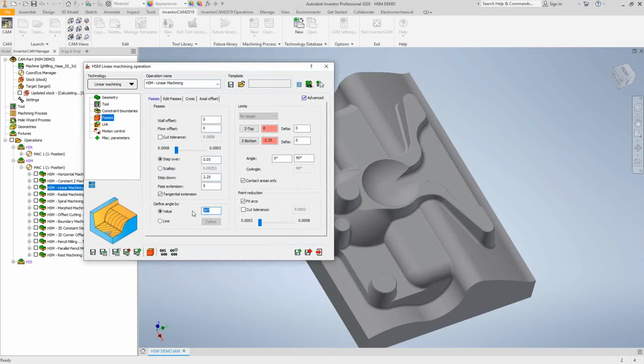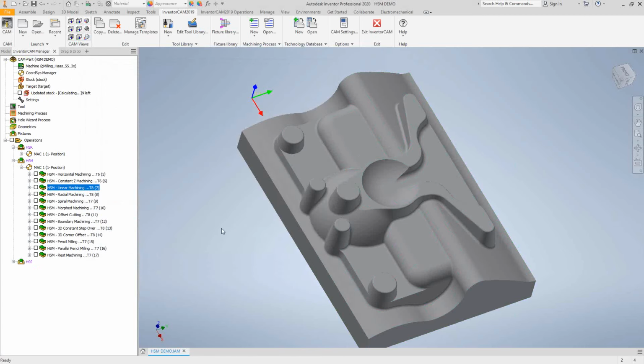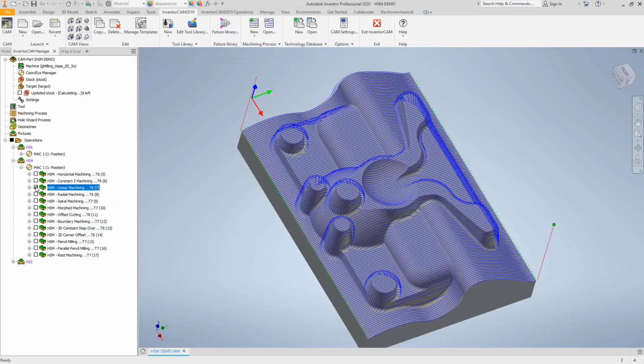Because this is a recognition toolpath, it's going to recognize the entire solid. If we wanted to, we could limit the travel of the tool using these angle limits, so it doesn't have to do everything. It can look at the solid and eliminate anything that's purely vertical, purely horizontal, and so on. In this case, I've done everything. But this is a good example of why I mentioned that each technology, each option, should be chosen relative to the geometry that you're trying to machine.